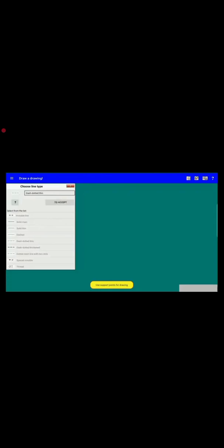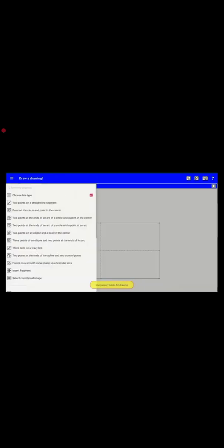Let's continue drawing. Let's choose the line type, solid main, the type of the graphic element, circle. Let us activate the Control button, which will force the application to create this supporting point simultaneously with anchoring the graphic element to the supporting point. For the second circle, we first indicate a point on the circle, and then turn off the mode of simultaneous creation of new support points, since we use the center of the previous circle. We fix the circles by the dimensions.